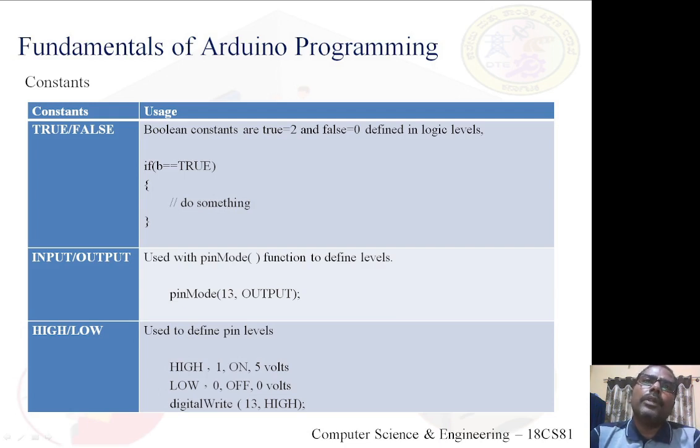I said through the pinMode method, I can configure any of the digital pins as an input or as an output as I require. So the keywords INPUT and OUTPUT are constants. Also, we have the other keywords HIGH and LOW, which are constants.